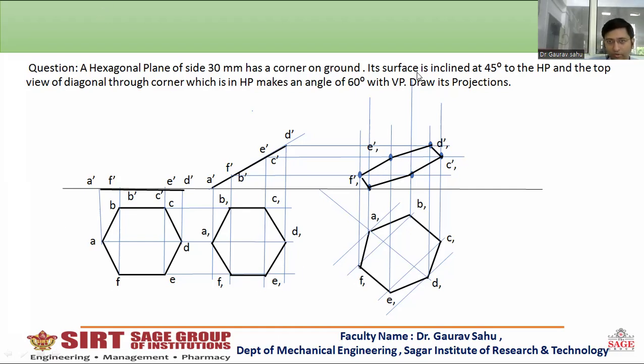So this is all about the question of a surface inclined to both the planes. Just remember, 90% of the question is solved when you have planted the first diagram. If you can imagine the diagram, you can work over here. So the procedure is that first imagine the diagram, take a paper from your vicinity, prepare a relevant shape of the plane you are tackling, and then start placing that paper on your table.